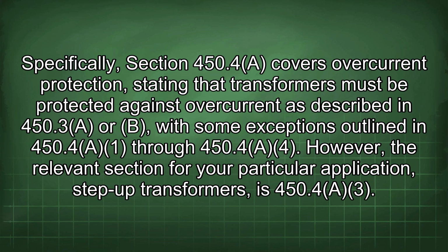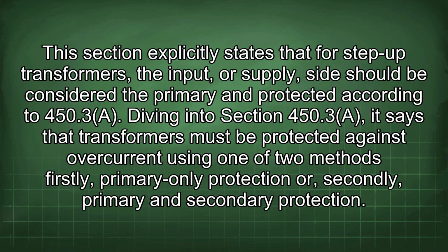with some exceptions outlined in 450.4(a) through 450.4(f). However, the relevant section for your particular application, step-up transformers, is 450.4(a)(3). This section explicitly states that for step-up transformers, the input or supply side should be considered the primary and protected according to 450.3(a). Diving into section 450.3(a), it says that transformers must be protected against overcurrent using one of two methods: firstly, primary-only protection, or secondly, primary and secondary protection.